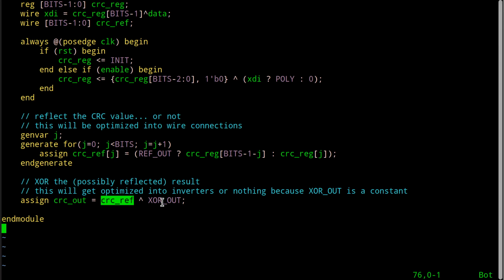And inside the FPGA, a lot of times you have these true and inverted outputs of all these D latches all over the place inside of the FPGA. So you usually have the true and the false ones available at all times. Anyway, it should be able to do this without actually using any more LUTs, although that would depend on the FPGA very heavily.